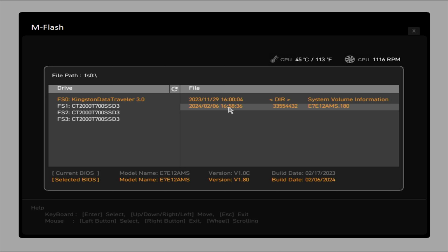We can maybe limit our fan speed. So for example, we don't want it to get to 100%. So eventually it will top out, but it will only top out at 70%, which is what you can see there on the left panel. And you might want to do that further down the range. So you might want 70% fan speed, which is on the left, from maybe the same point. You can just have a square graph. So at 60 degrees on the bottom for our CPU, it actually dials up our fan speed to 70%. So that's a pretty cool way of customizing your fan speed.